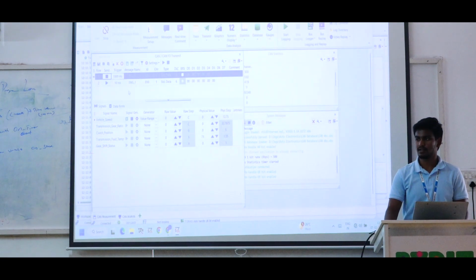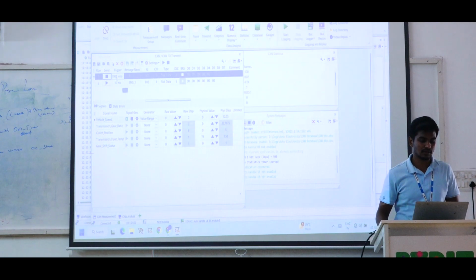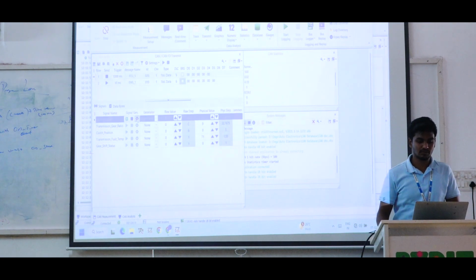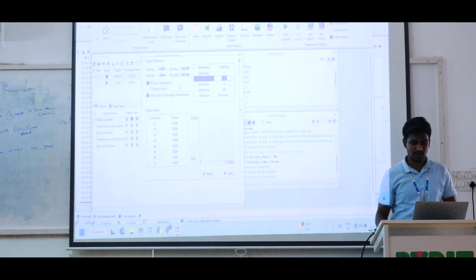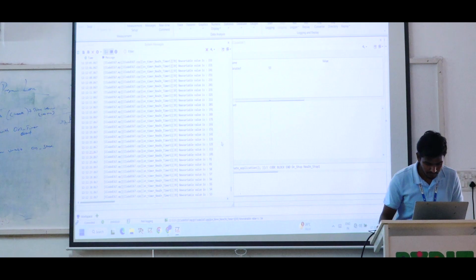So 1000 milliseconds. Go to the previous tab, where the transmitter is. It is manual and periodic. So change the trigger value to once every 1000 milliseconds. And in this value range also, you have to set the step size as 1 and then the hold time as 1000 milliseconds. So all of you have to set it as 1000. After this, now you have to see.